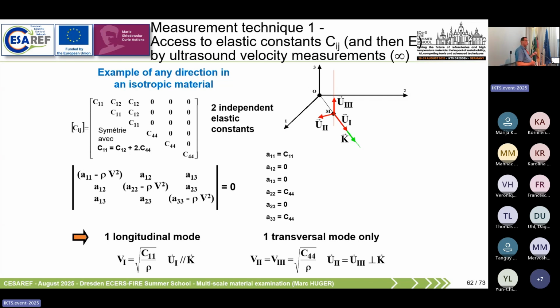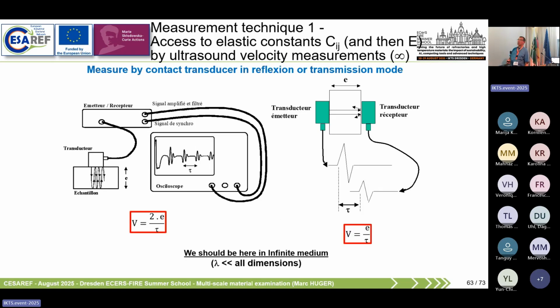If you look at what you measure and take care about your measurement, normally you should obtain the right value of elastic property, and the same for the different experimental devices. If you do measurement with ultrasound, typically the strain engaged in the measurement will be very low, and you will not damage your material if you propagate ultrasound inside your system. And then you have a lot of chance to obtain a higher value of Young's modulus with ultrasound.